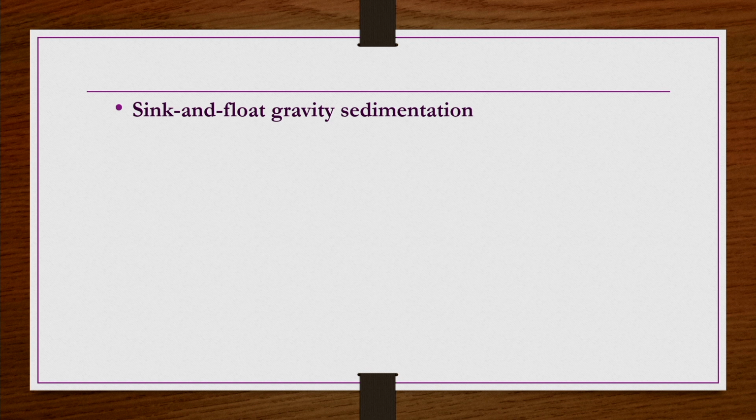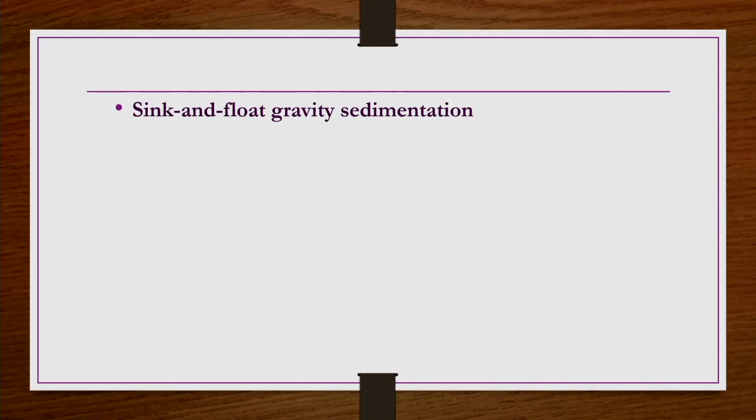Then what you can do is find a solution or solvent which has a density in between these two. Then when you allow these particles to flow along with this fluid, whose density is in between the densities of these two types of particles, the heavier particles, or the particles of higher density, may be settling at the bottom, and the lighter particles, whose density is smaller than the fluid density of the solution we have taken, may be suspended or floating on top of the liquid.